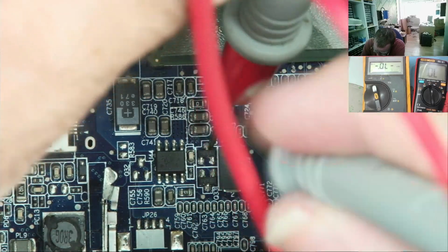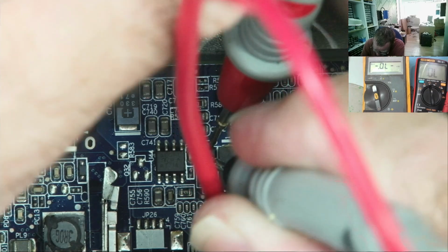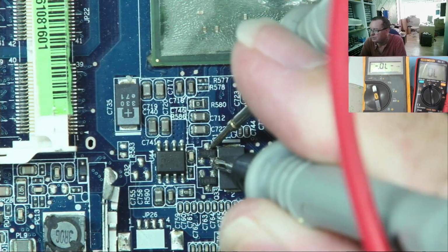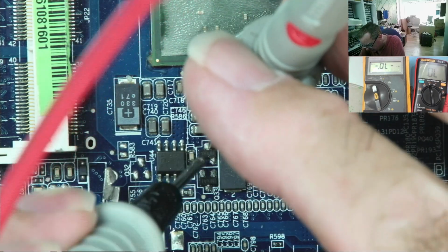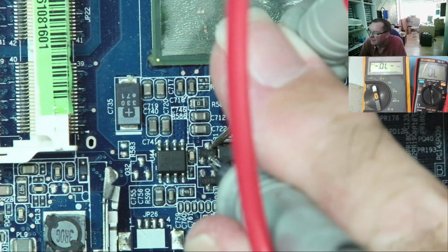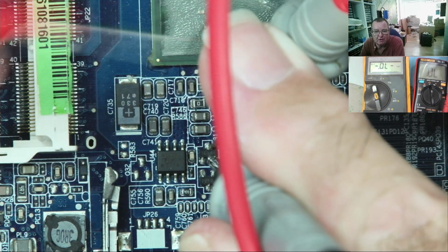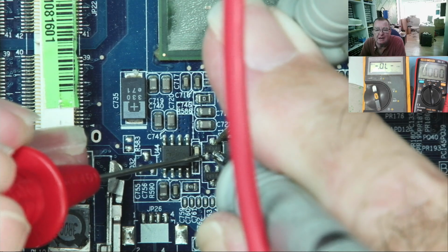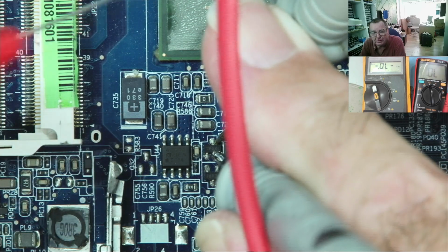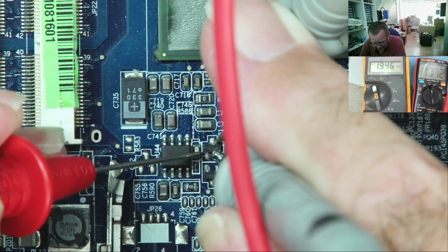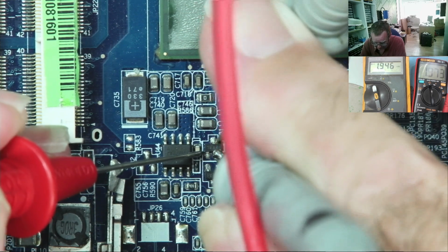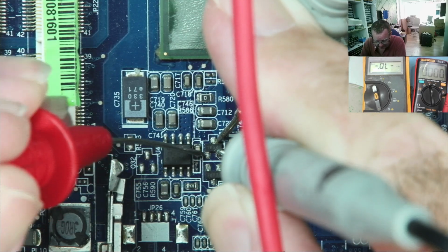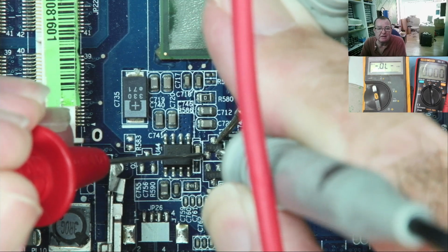So what we do is we connect our Aneng meter across the drain source. And we get the wire out of the way so you can see what I'm doing, okay? So if I can get it just in position, I can connect the Aneng across there. Now I can use the diode mode to put a voltage on the gate. Watch. See? Look at the Aneng, it's turned on. I'm not seeing a reading on the Fluke because the gate is effectively open circuit. It's got a high resistance. I think I've probably slipped a bit. Let's get back onto it. Yeah, there. Okay. So you can see I can turn that MOSFET on.